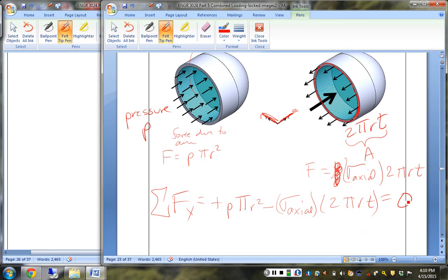because we were still doing a statics problem. And we can solve this guy out for axial stress. And that ends up being this guy over this guy, 2 pi rt. All right, so pi's go away. That squared goes away, and that guy goes away. 2 pi r is the circumference, okay? And the T is the wall thickness. So that's the area of the metal part.